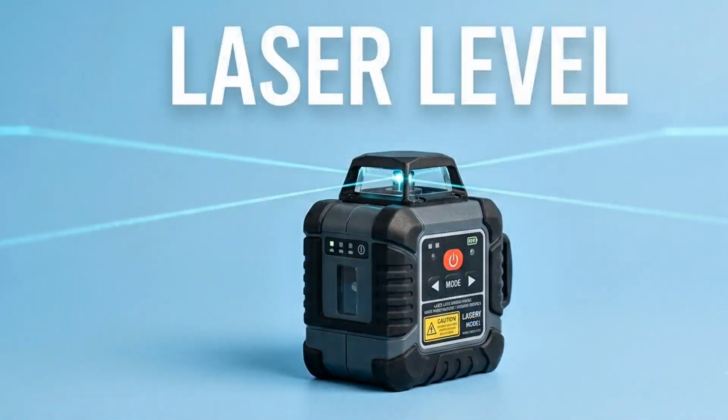A laser level projects perfectly straight horizontal, vertical, or cross lines onto walls and other surfaces. It is one of the most valuable modern measuring tools because it allows multiple workers to align their work simultaneously. Contractors use laser levels when installing ceilings, tiles, cabinets, windows, partitions, electrical systems, and plumbing systems. Accurate laser lines improve efficiency, reduce errors, and produce professional quality construction work.